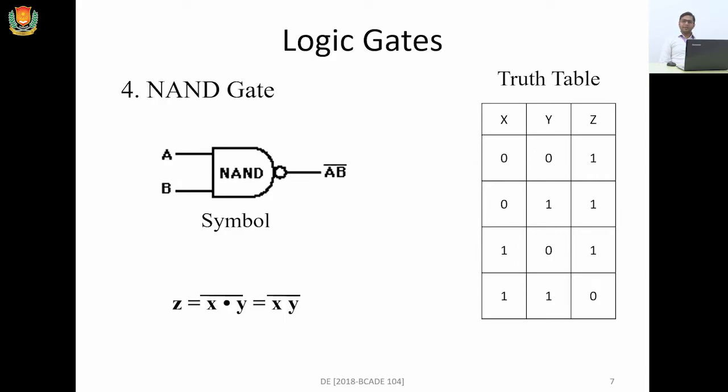Input 1 into 1. Okay. It is just inverted to the AND gate. The truth table is just inverted, or complement, to the AND gate. Okay. Let's see. The Boolean expression for the logic gate is X multiplied by Y, that is the AND gate, and the whole bar. Make a note, it is a whole bar, not X bar and Y bar.